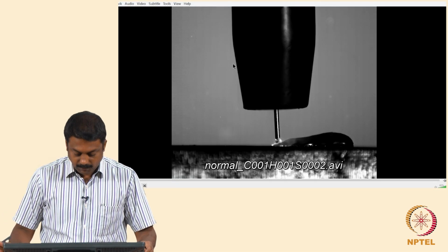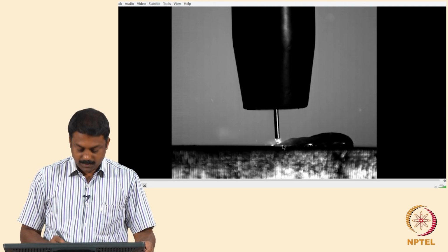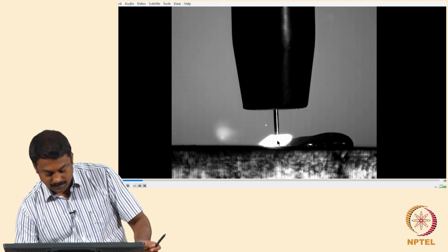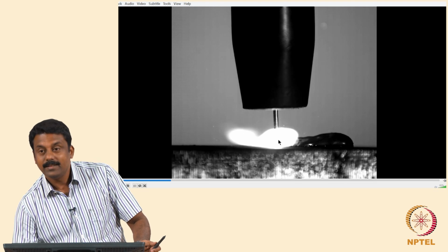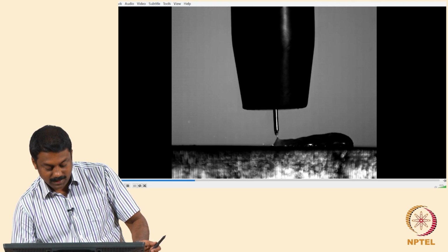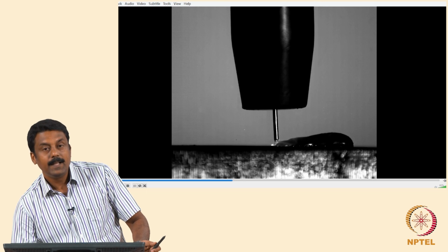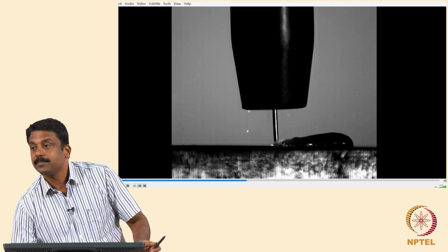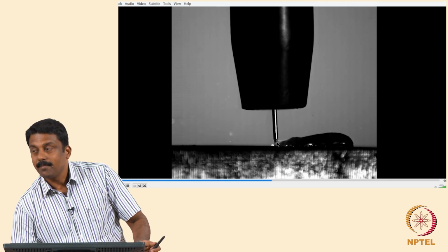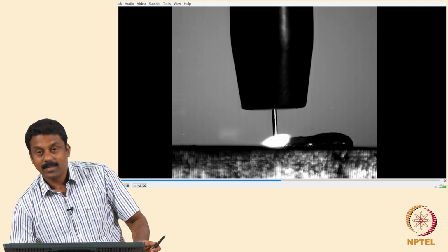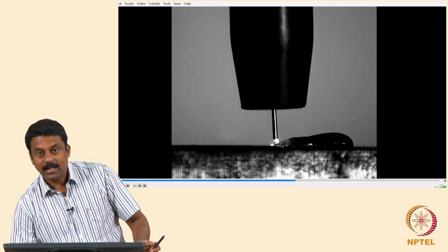So, you see the transfer. What is happening here? You have an arc. Transfer happens by the short circuiting, and during the short circuiting event there is no arc. You see that? So, you establish the arc with an arc length, and then you switch off the arc the moment the short circuiting happens, and then you transfer the droplet by the surface tension of the liquid pool. Yes, it is clear? So what is the explosion? The explosion is the arc. Okay, so it comes after the short circuit.